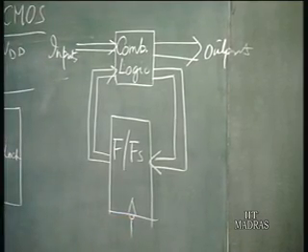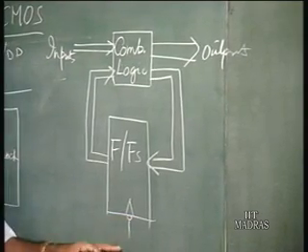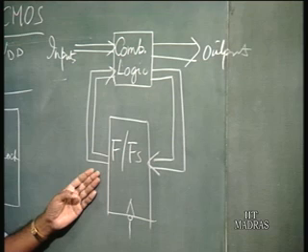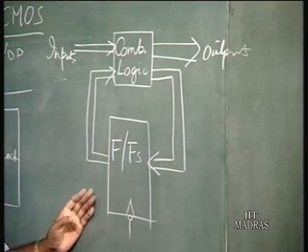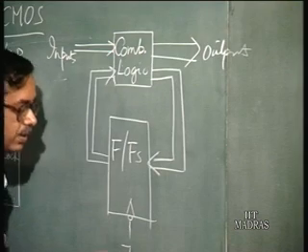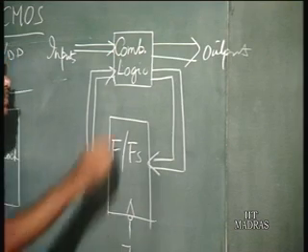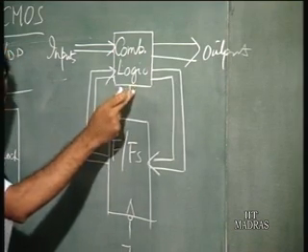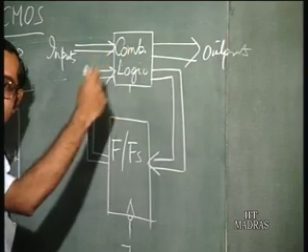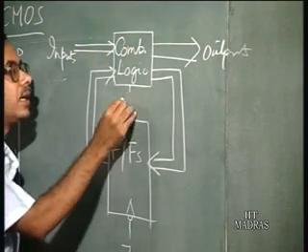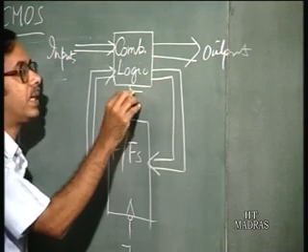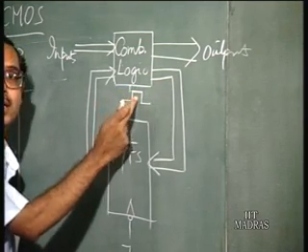a negative edge triggered flip flop. So the changes, whatever they take place, they take place at the negative edge of the clock pulse, when the clock goes from high to low. Now, suppose here you have a digital circuit, a dynamic logic circuit, where the evaluate phase is when the clock goes high.